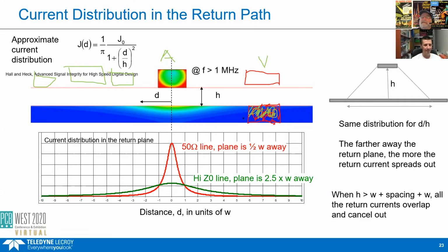And we call this behavior, we call this noise source, when I have a screwed up return path, so it's anything other than a wide line, a screwed up return path and multiple signals sharing that same screwed up return path, we call that ground bounce. That's what ground bounce is. It is a type of crosstalk that is dominated by the shared return path. And that says, how do you fix ground bounce? How do you eliminate ground bounce? It says, number 1, don't screw up the return path, and number 2, don't share return paths. That's the secret of solving ground bounce problems.